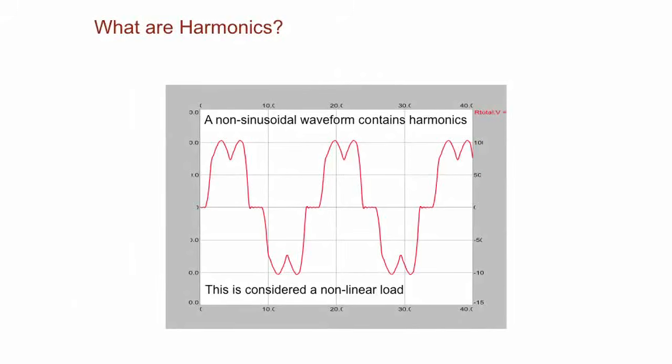This is a nonlinear load. This is what a VFD looks like: if I put a current clamp on that VFD and look at the currents going into that drive, this is what I'm going to see, these two bunny ears. I like to call them bunny ears, or the two camel humps. Basically that's the conduction of the drive. Interesting thing: this drive's pretty lightly loaded. How do I know that? Depending on how far the center peak dips down tells you how heavily loaded the VFD is. The more load on the VFD, the more you'll see that trough go down.